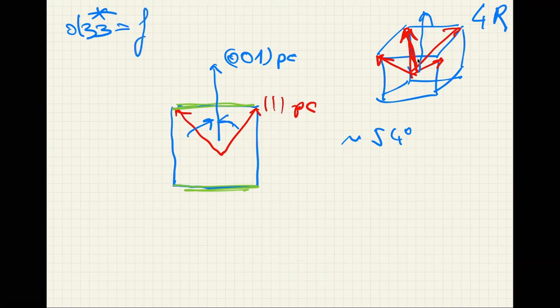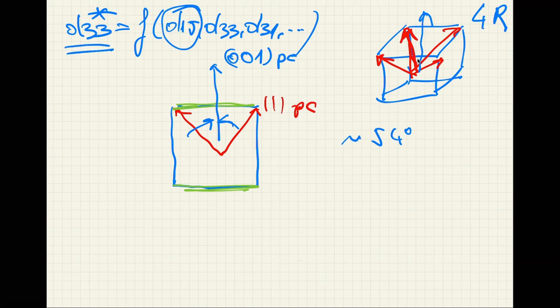It is a function of d15, d33, d31, and so on. I think d32 coefficients in a rhombohedral phase, and it is d15, which is, because of polarization rotation, particularly large, which will give you large d33 in this direction. d33 is very small along the polar direction, but becomes large when you apply field off the polar direction.